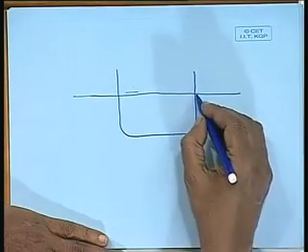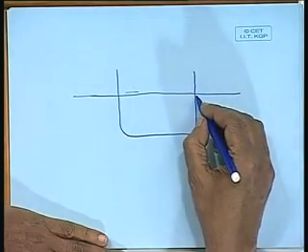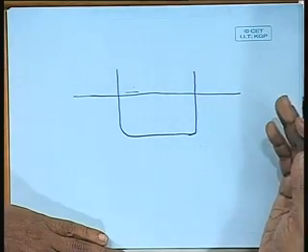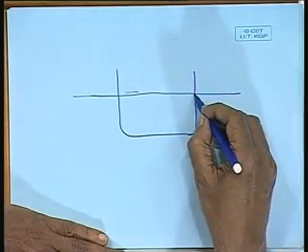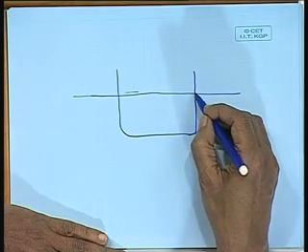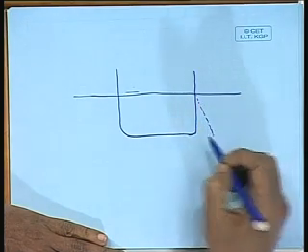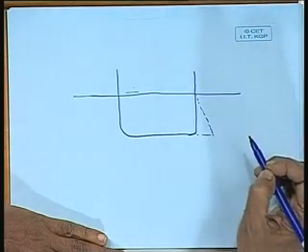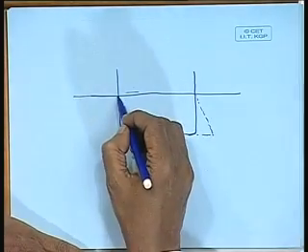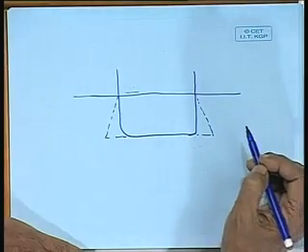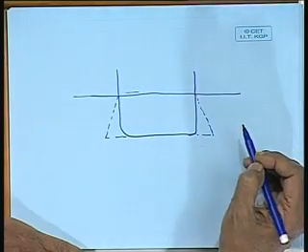Now, if you look at the pressure distribution on this body, since we have seen hydrostatic pressure rho g h, the pressure here will be 0 at the interface, and it will go on increasing proportional to h, right, and the same will happen on this side. And we also know that the pressure acts perpendicular to the body everywhere.